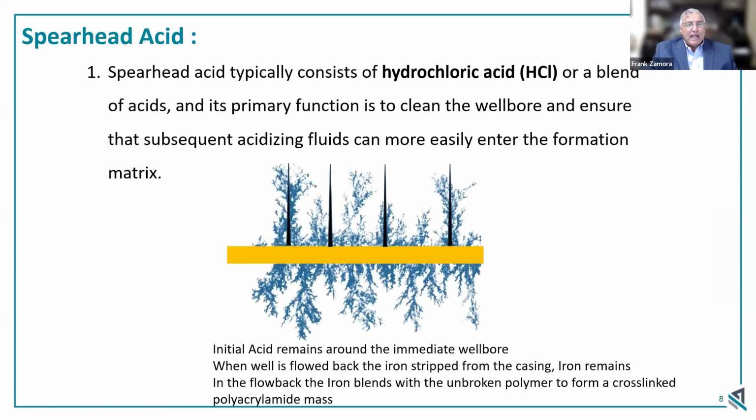So when we talk about the spearhead acid, there was another operator who actually did some work where they ran the spearhead acid, and then afterwards they caught water samples of all the fluid that was coming back, and as they were captured, they measured the amount of iron, starting early on right after the frac and then progressing over a period of time. We always think that a spearhead goes ahead of the frac, gets pushed further out into the fracture, and we never see it again. Well, that's not exactly what's happening.